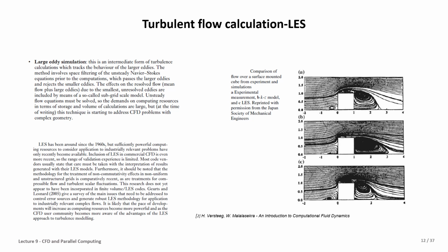Then another example of a CFD solution for the largest scales is called LES. Indeed, in LES, based on its name, large eddy simulation, we use some filter to remove and ignore some scales of the solution, using a subgrid scale model.